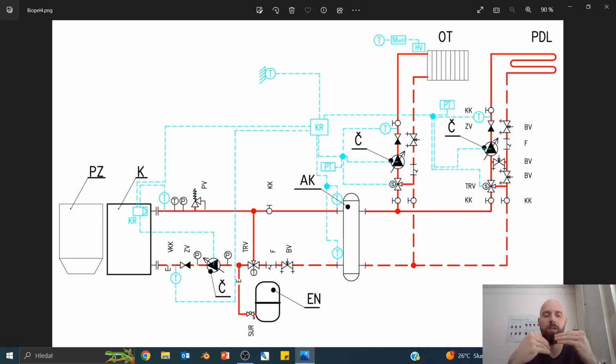then you can use it with the return water protection function and select, let's say, 65 degrees as a minimal return water, which goes back to the boiler. By this way, you want to keep the water which flows into the boiler from the system as hot as possible, so the boiler is not cooled down by cold heating water, and you protect the boiler as well against corrosion,